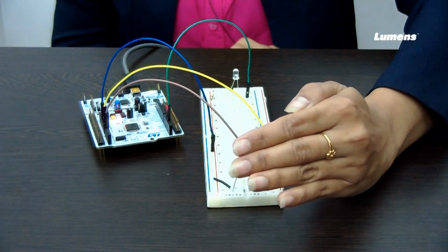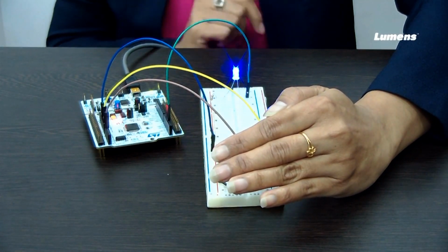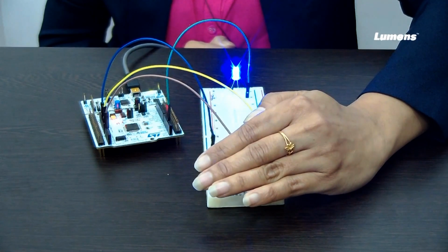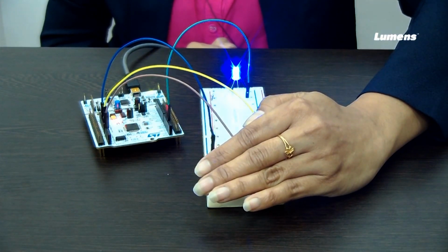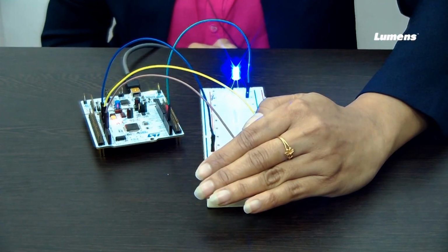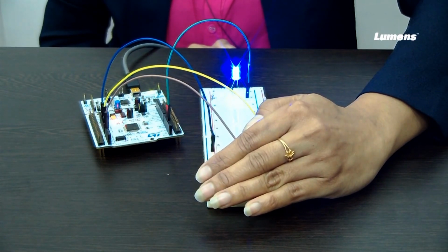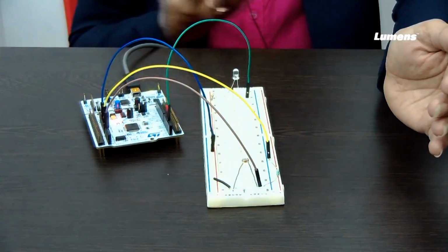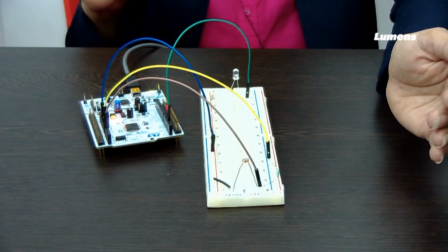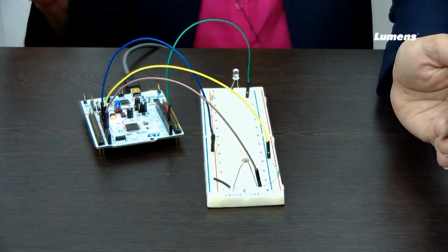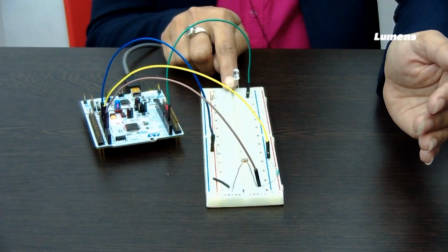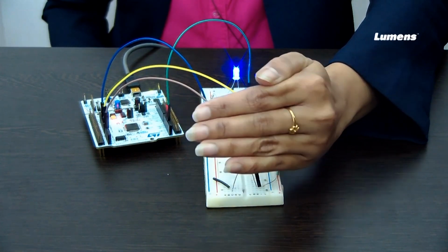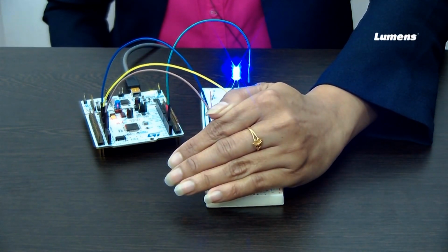Okay. Now, see, it glows when there is less ambient light. Now, it is glowing in full when the ambient light is very little. Okay. So, this is the experiment with LDR: by sensing the ambient light, how do we actually switch on the light with different intensity. So, this we have simulated using this LDR. So, I will just show you once more. This is glowing, but not with full intensity, but you see this is glowing with full intensity.